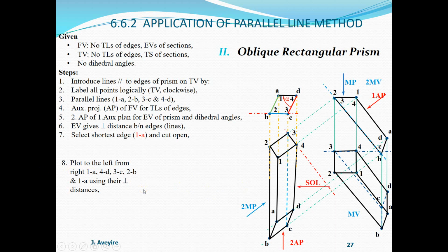Okay, so now here, cutting and projecting in that way, first to get 1A by projecting, that's a true length. Then I need the distance between that, so 1A and then 4D, that is the perpendicular distance. I pick that distance over there, then draw the line, then project 4 to obtain 4, and below D to obtain D. Then the next line that comes is 3C.